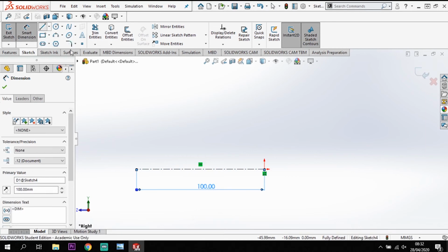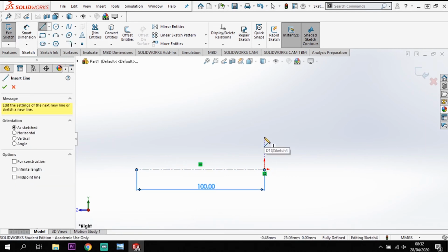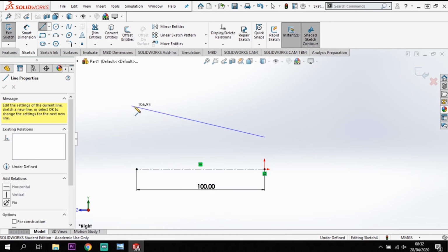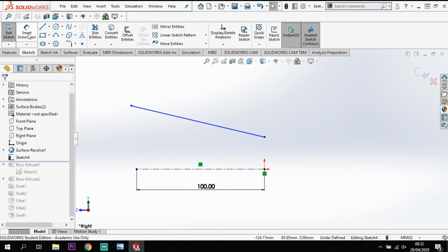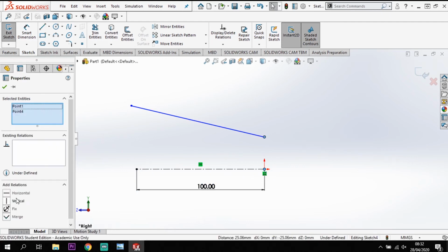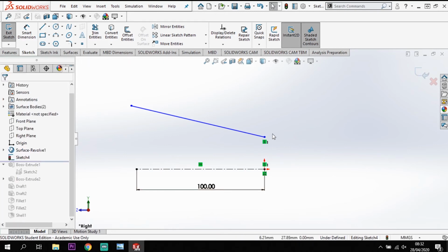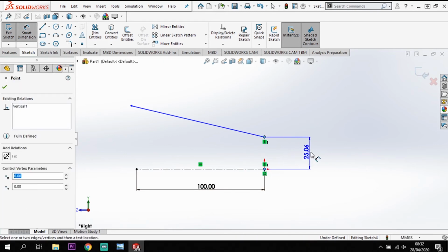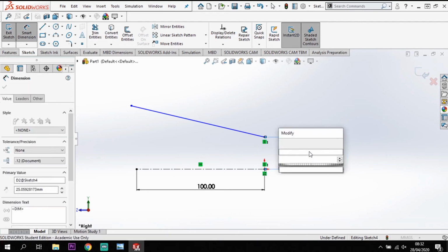Now this line is going to come on line with my origin, but up here at an angle. So I want that point there in my origin to be vertically aligned, like so. Then I'm going to set the offset distance between them 2 points, which is going to be 20.